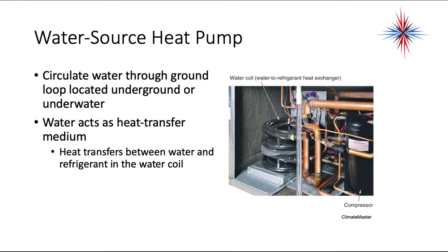The water source heat pump circulates water through the ground loop, underground or underwater. Water acts as a heat transfer media. The heat transfer between the water and the refrigerant occurs in a water coil heat exchanger. Okay, so this is a picture of the internal components of a water to air system.